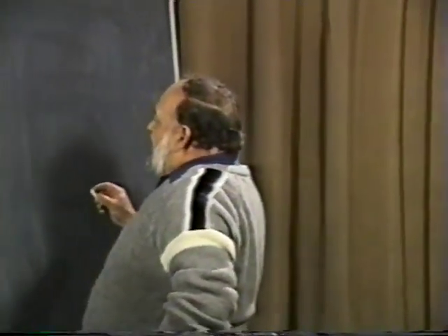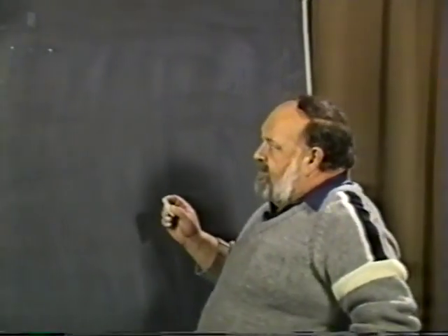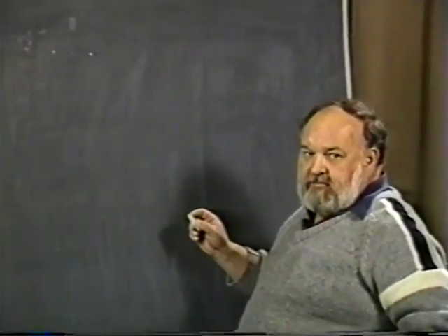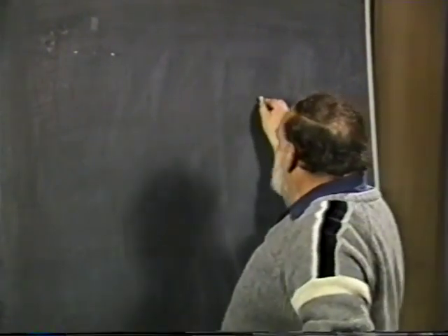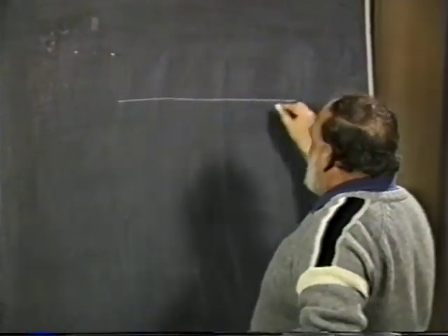There are a couple of key things you ought to be certain you understand when you're dealing with an all-flying tail. Let me go over to the board here and I'll show you just exactly what I'm talking about. It can be done other than using a symmetrical section, but it's strongly recommended that when you go to an all-flying tail, use a completely symmetrical airfoil section.